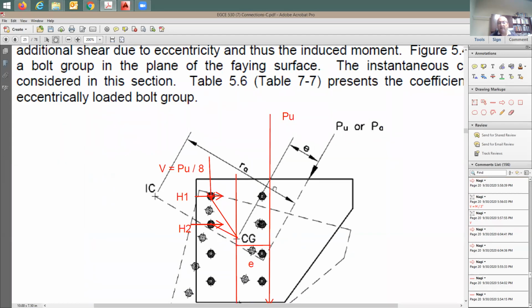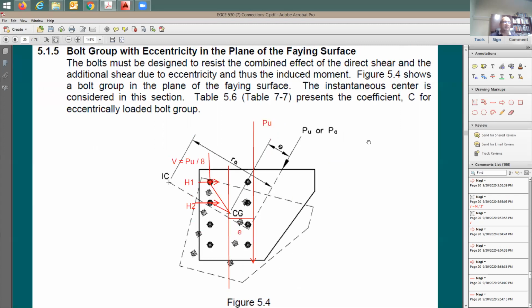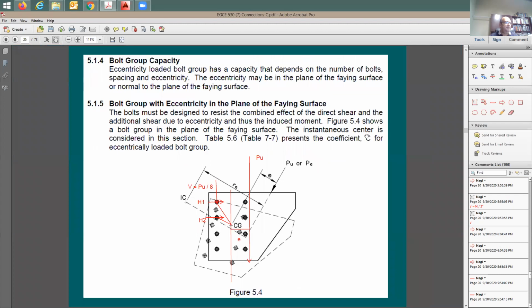The other simple example was 2 bolts. That was just simple. I was able to split the force, the rotational for the moment, and put it in 2 bolts only. But here it's going to be more complex. There's more than one theory here to finish this business.